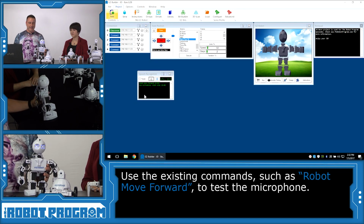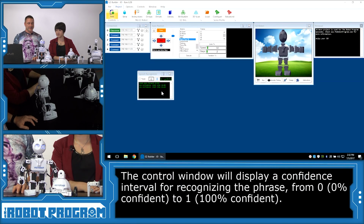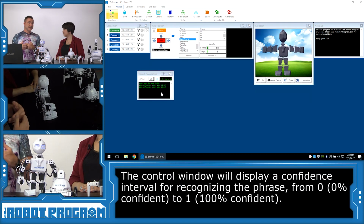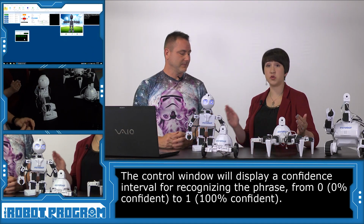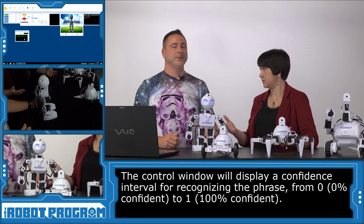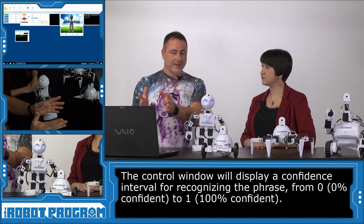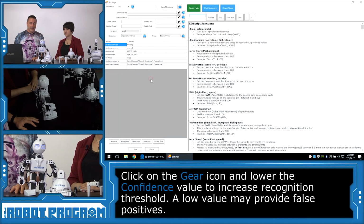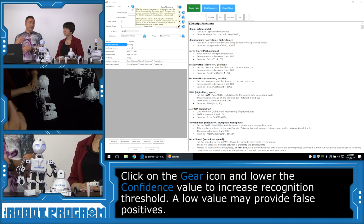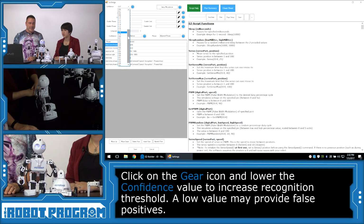Okay. Because it didn't hear me, and you can see it says low confidence, robot stop, and it says 0.66. That's because the computer was only 66% confident that it heard what I was going to say. So we have a value from 0 to 1, but 1 acts like 100%. You bet. So if you don't have an external mic and you want to compensate for the microphone inside of your computer not being that great, we can click on the gear, and at the top it'll say confidence. This is the minimal confidence value that will register for the command that it thinks it heard. So right now we're at 87%. It's pretty high. So we saw 0.66.